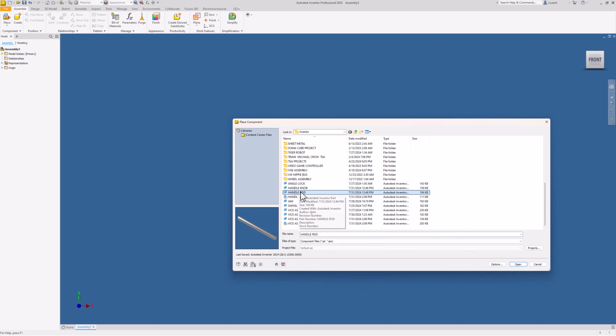I'm going to click that, and then up in the inspector, make sure you hit activate contact solver. And so now when I did that, it doesn't allow those parts to go through each other. So it stops when it gets to the next surface. So that's kind of what we want.